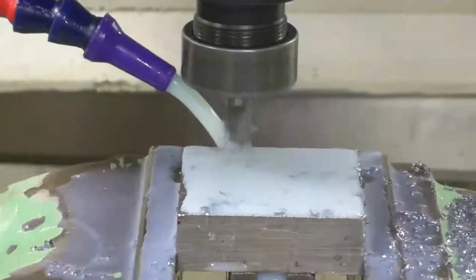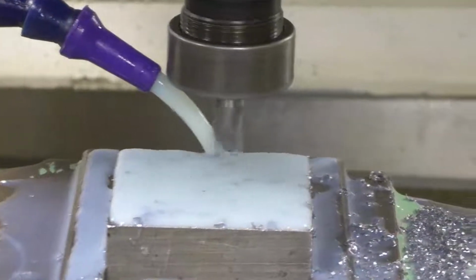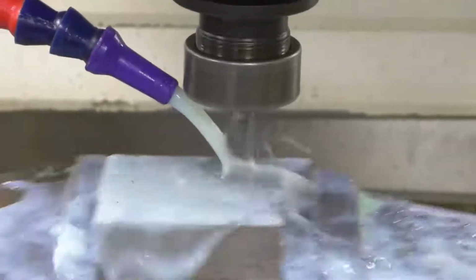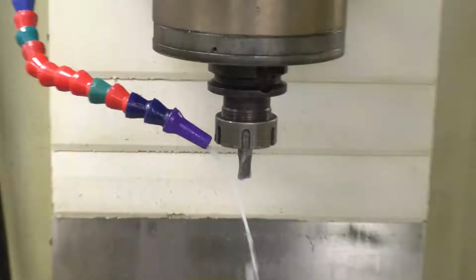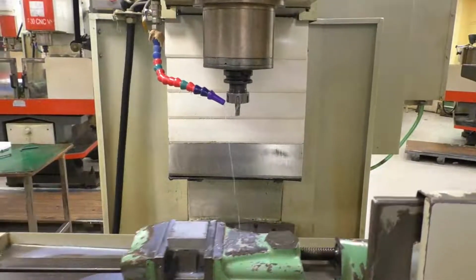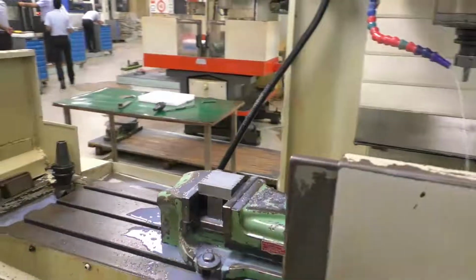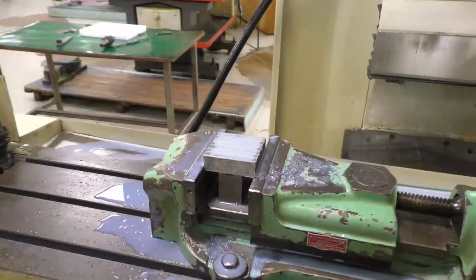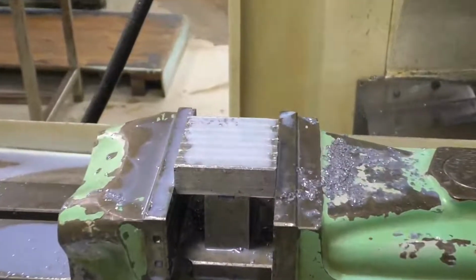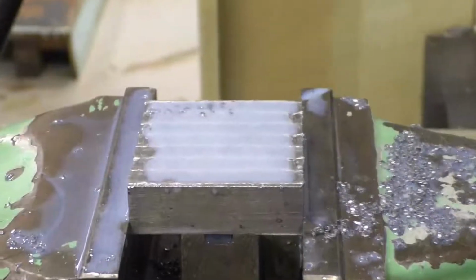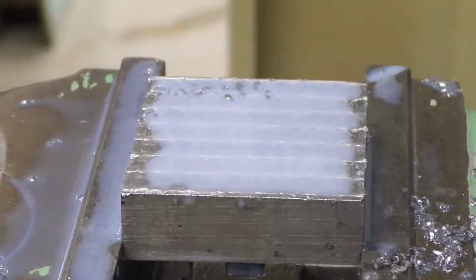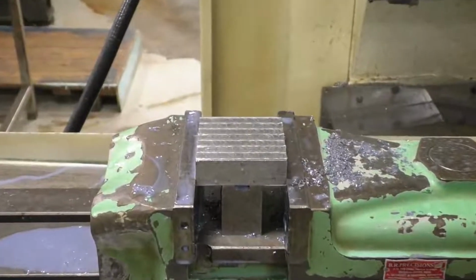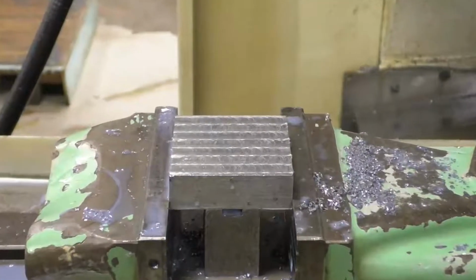And you can see once the depth is completed, as per the program, the machine will stop, the spindle will stop, I can say, and the homing will be done. And you can see 1 mm of material has been removed from the surface of the job in a facing cycle. Here coolant is there, we'll clean it and we'll see how it looks. As you can see over here, after the coolant and the chips are cleaned, these are the cutter marks we are getting. So in this way the facing cycle is done.